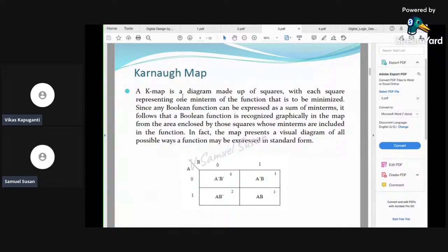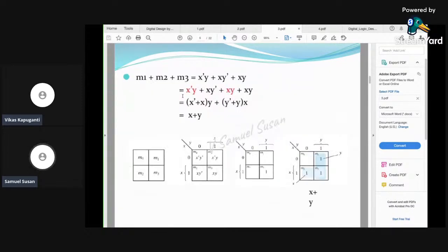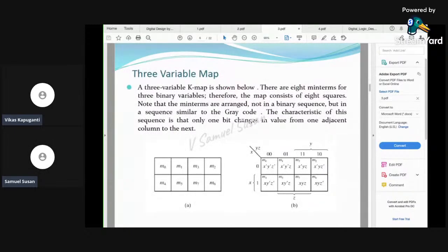We'll explain that. So this is the Karnaugh map for two variables. We can directly go with the three variable. I guess most of you know what a two variable map is. So go to the third variable or else fourth variable map. When you draw these K maps, make sure that the order, or else the map structure, is correct, because I see common mistakes when they write the numbers inside the K maps with minterms, that is 0, 1, 2, 3 and so on. So go to the next slide.